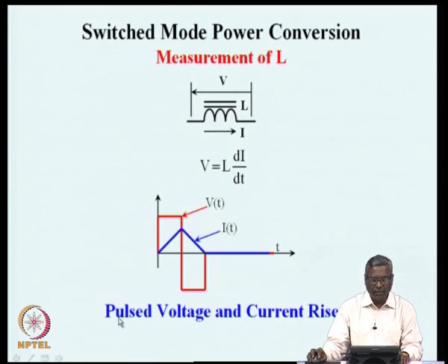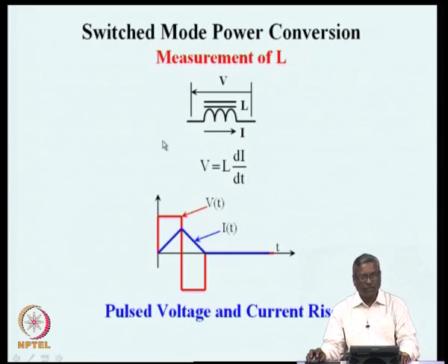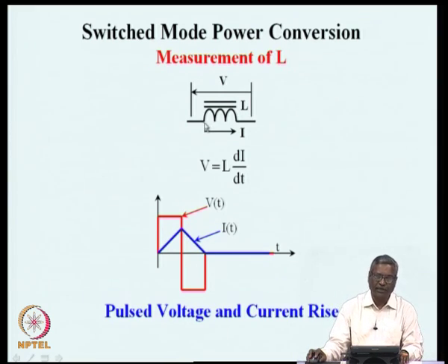This is called a pulsed voltage test, or a pulsed voltage and the measurement of the rate of rise of current. So, this is one very reliable way of measuring inductance, and this is also a very inexpensive way of measuring inductance. Unlike many equipments which are needed to measure, this is a very inexpensive way.